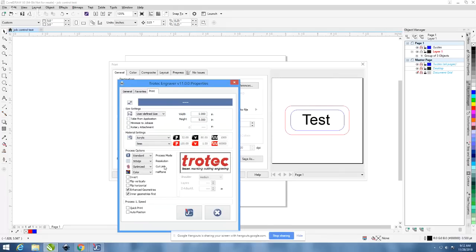And Anthony, that's if you don't have a cut line in the artwork, right? That's right. Yeah. But usually, to have more control, we would put the cut line in the artwork file. This is just for a quick test. It's a great feature to have. It's usually used on rubber stamps actually, where you might not have a cut line on the stamp. So the optimized option works very well to avoid the back printing that you would get on a rubber stamp if you didn't have a close cut background.